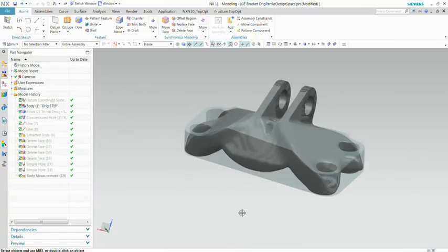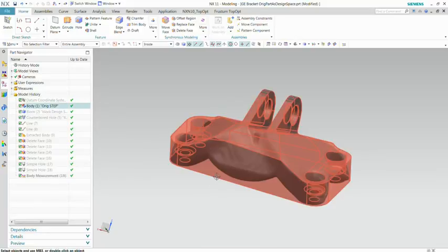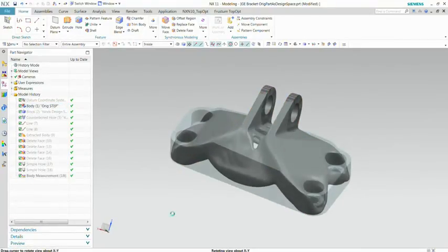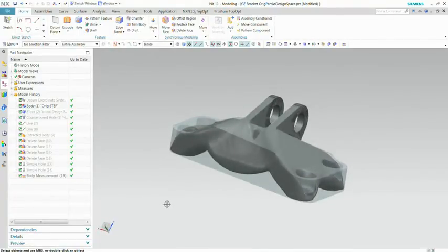Another example of an optimization is, for example, this bracket. It was used for a contest on Topology a few years ago, but here you see, for example, the design shape of a volume where we allow to have material, and you see here inside the optimized shape of, for example, this bracket. So it's a method that gives you, in a very fast way, already some shapes that can inspire you for your final product. And because of the precision of the result, maybe it's already good enough for direct production purposes.